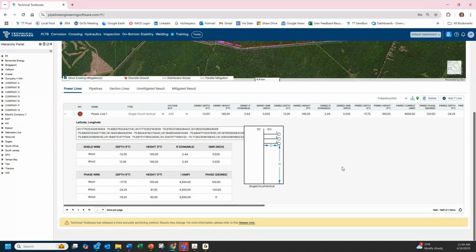Now, what you've got to be concerned about with a bundle like that, underground systems, is the grounds themselves. They have a tendency to open up from corrosion, and from damage, lightning and things of this nature, and they also have a tendency to discharge. And if you happen to be where they cross, you could have some significant effects.